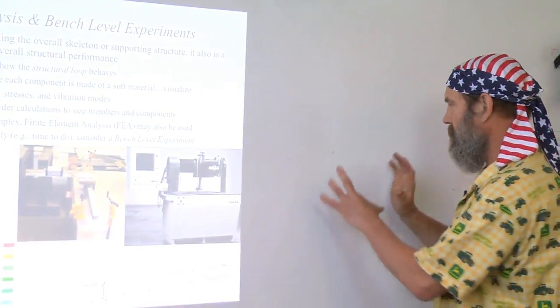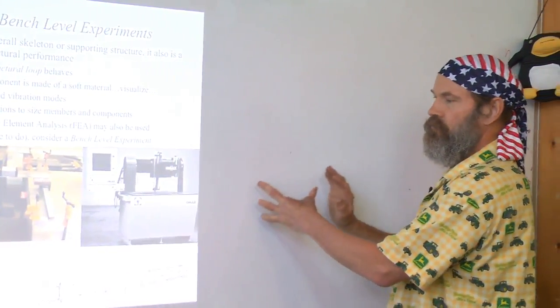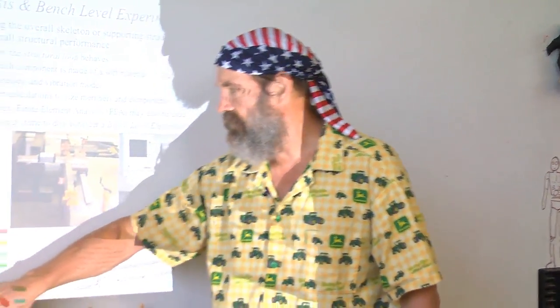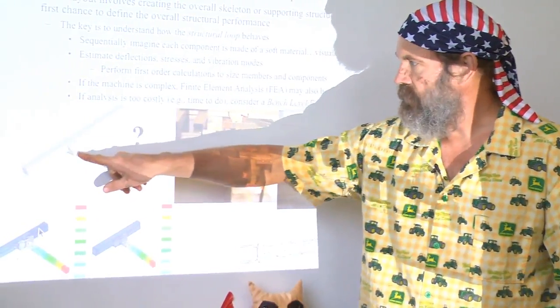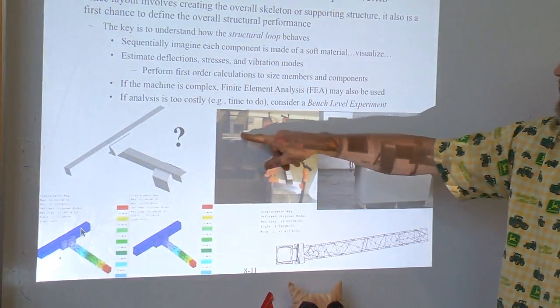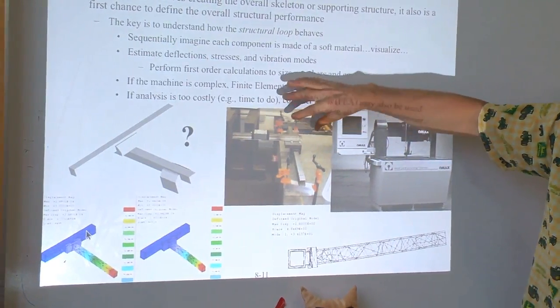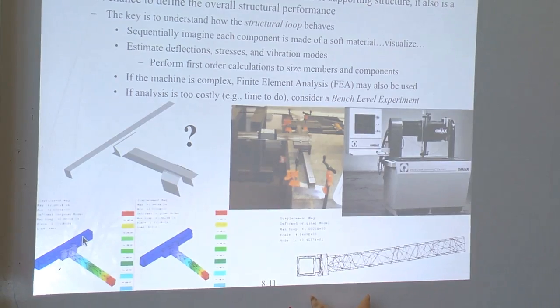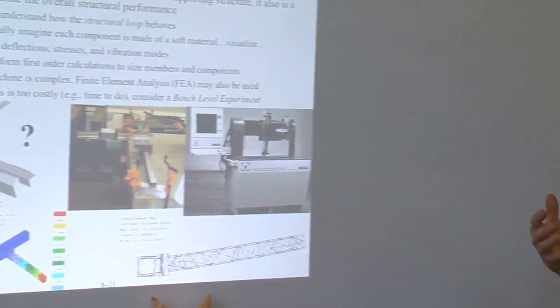And the lesson here is we went from concept sketch, first order analysis, solid model, finite element analysis to verify this type of joint structure, what the stiffness was, then a mock-up in the lab where we actually built one and did stiffness tests and dynamic tests to get our early results. Things actually worked out fine and very nicely for the small machine size we're looking at.